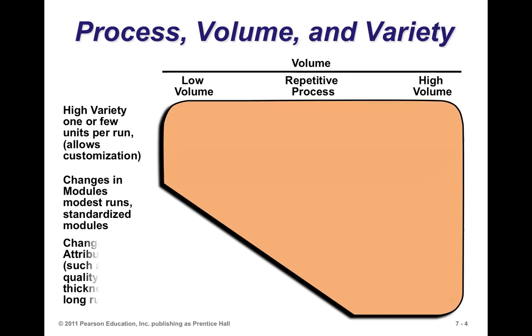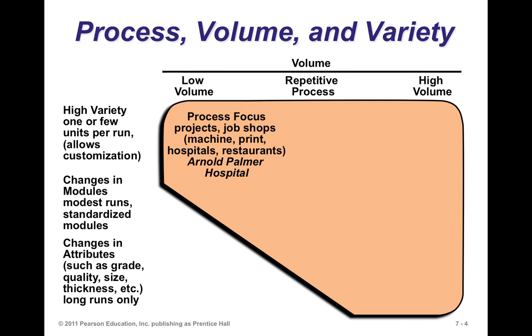In classic production systems, we often talk about three broad categories of processes. Those three broad categories came about as a result of a need to trade off between two very important variables. One is the volume of product that you could produce, and the other one is the variety or flexibility of that process to produce a number of different types of products. We often see those two as a trade-off. In other words, if you want high volumes, then you have to expect low variety. If you want high variety, you have to expect low volumes. So if we examine the trade-offs between those two variables, we get the following types of processes.